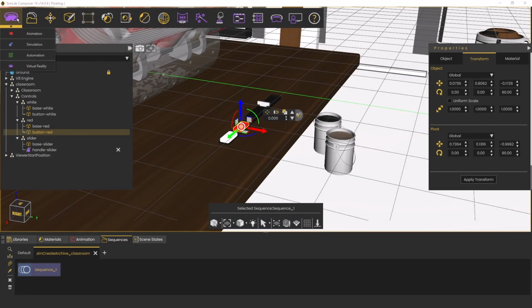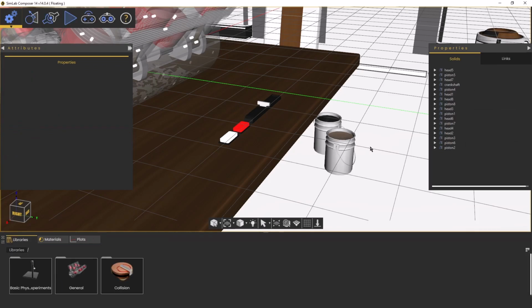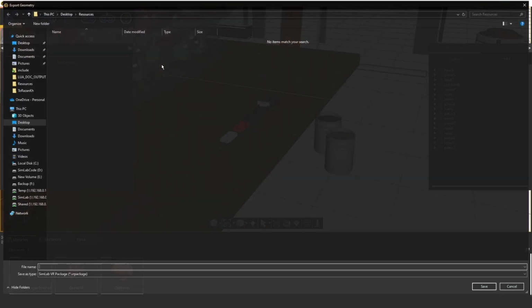Now, let's switch back to the simulation workbench to export the experience to VR package, and start the co-simulation. Go to co-simulation, then export VR package. This option exports the simulation as a simulation-compatible VR package. Ensure you export using this option from the simulation workbench.